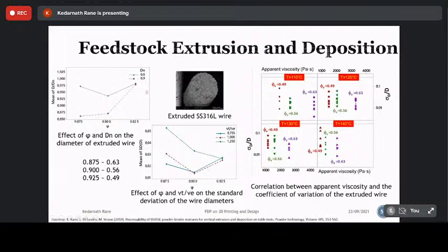But you can see the clear trend is that at higher nozzle diameter, the process is not so stable, but at lower diameter, the shear rate is much more uniform at any solid loading, and you get the same kind of distinction. By the way, when you consider 1, it is no swelling.